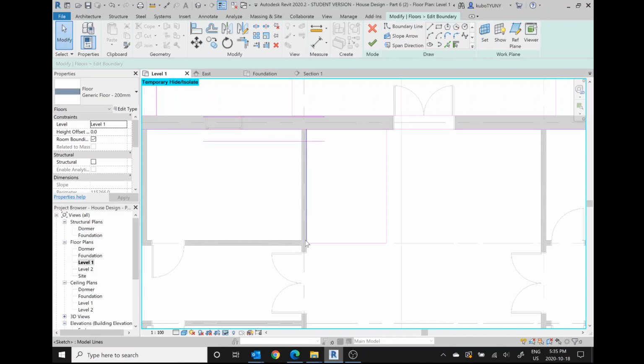It has to end up being a U shape that joins into the larger shape of our outline. So what I need to do is cut that part out. I'm going to pick this button here, which is split element. Click on that corner, click on that corner, hit escape twice, click that line, hit delete, and now we're good to go. So I'm going to hit the check mark.